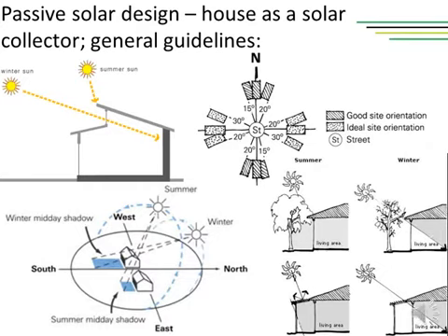Another important way of reducing energy demands of the building is by using passive solar design. This basically means that we should design according to local conditions, climate, topography, vegetation, orientation, and surrounding buildings. The general principle of passive solar design is the use of sunlight without active mechanical systems. These buildings are designed to let the heat into the building during the winter months and block out the sun during hot summer days. Ideal site location and house plan is maximally exposed to the sun from 9 a.m. to 3 p.m. in winter time.